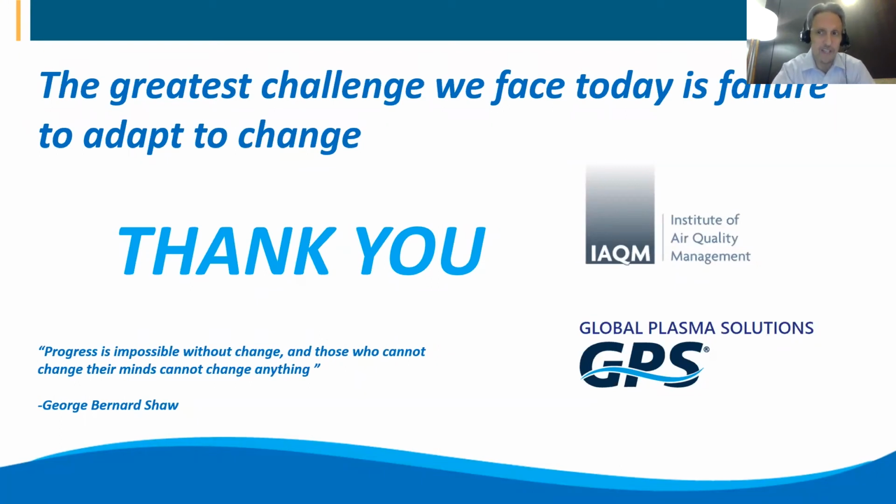As a manufacturer of needlepoint bipolar ionization, we have byproduct testing that we've done, and we have those reports available to the public. The number one concern on everyone's mind, whether it be ASHRAE or CIBC or any of the other organizations, even the CDC that are providing guidance on these technologies, is ozone. That's a no-no. And for sure, you want to make sure you apply a product that does not create ozone. Ozone will interact with all kinds of things in the indoor environment and create byproducts and help create particles, and are an issue of concern from a standpoint of the occupants in the space breathing it.